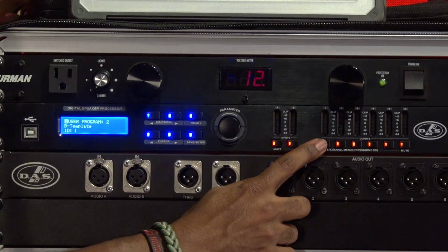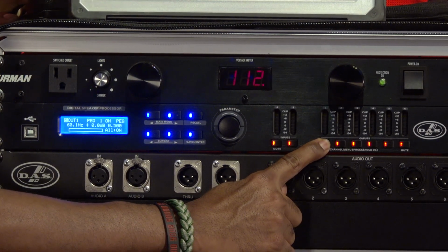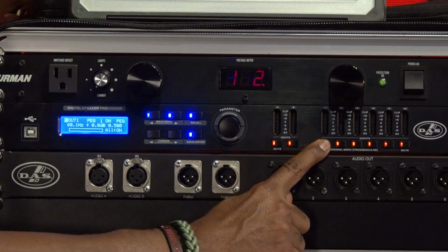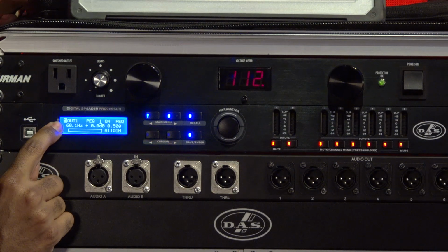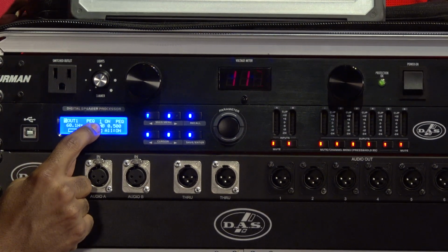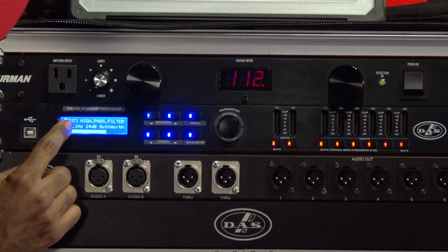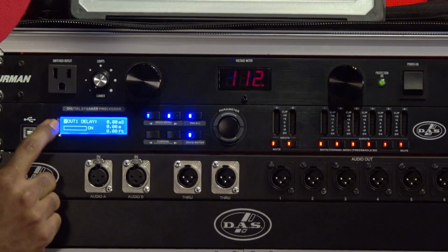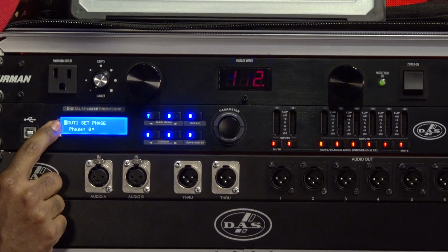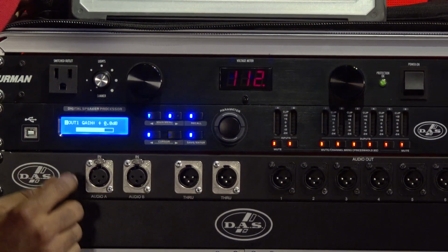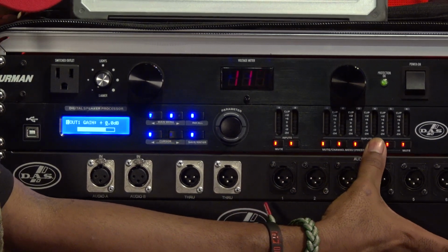And if I wanted to adjust an output, for example, which is typical, if I'm doing subs, tops, I press and hold, and now I'm in the edit mode. I'm on output number 1, parametric EQ. If I wanted to back up, I am now on output number 1. I'm doing the high pass filter. I can back up. Output, this is my delay. This would be my phase, and then the actual gain. So any output I press and hold,